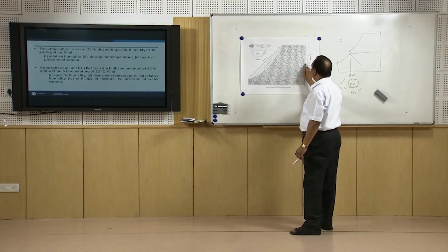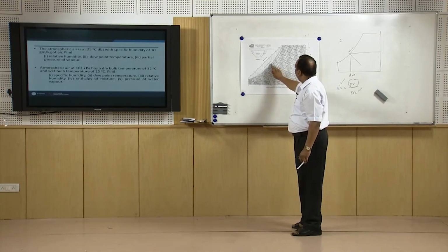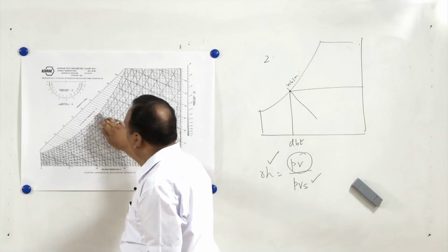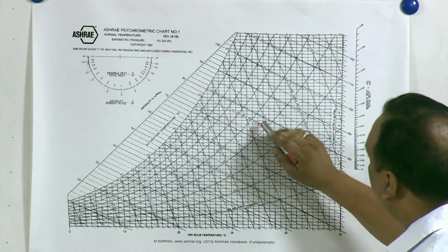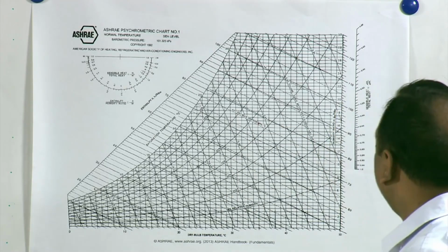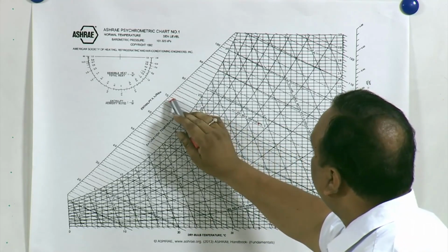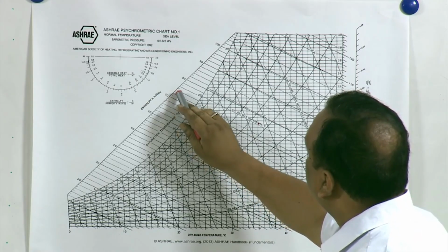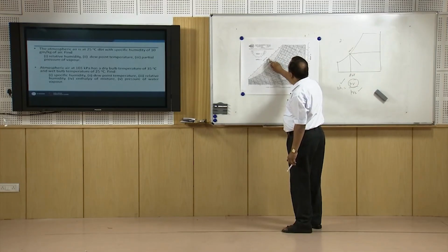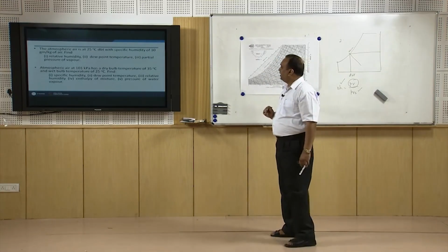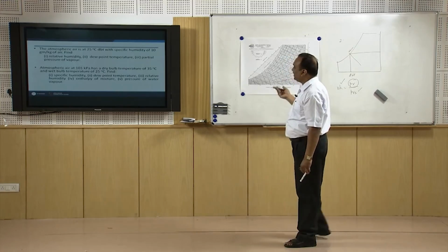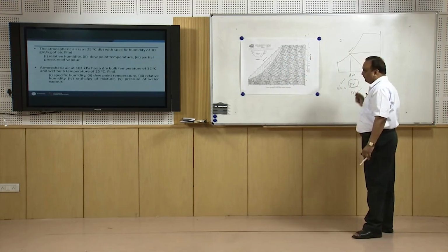For example, specific humidity on going to the right hand side, then dew point will go to the left hand side; dew point will be around 22 degrees centigrade. Relative humidity we can take from here, it is around 45%. Enthalpy of mixture, we can take here as 72, 74, 76, 76.5, and pressure of water vapor, again we can use the same formula, PV by PVS.